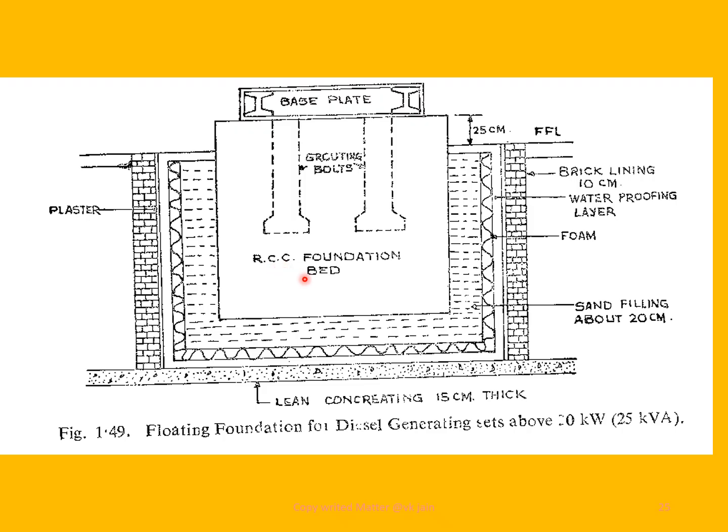a RCC foundation bed, and dimensions are given here. This foundation is kept away from the structural element through linings. Now you can see this area is filled up with sand cushioning. So this provides a spring type of action when the load comes over this sand area. This is sand filling about 20 centimeter in width all around.